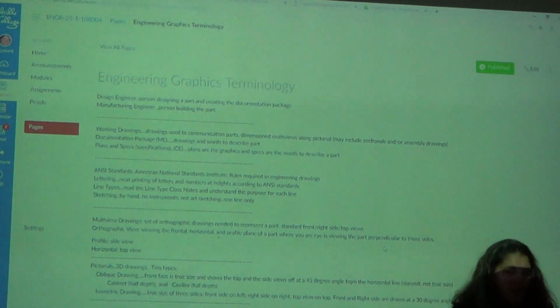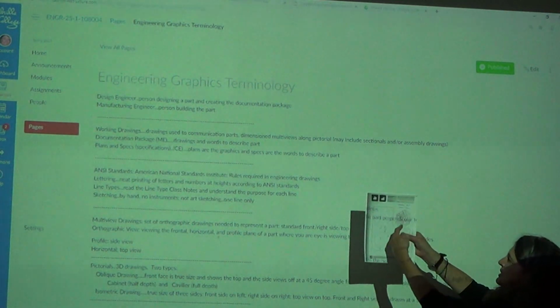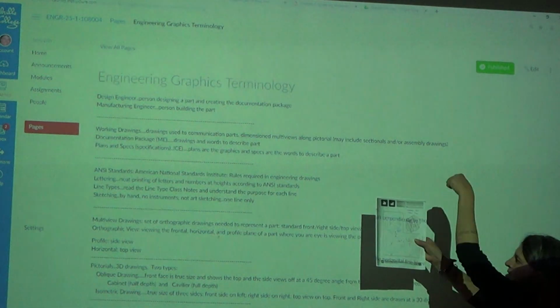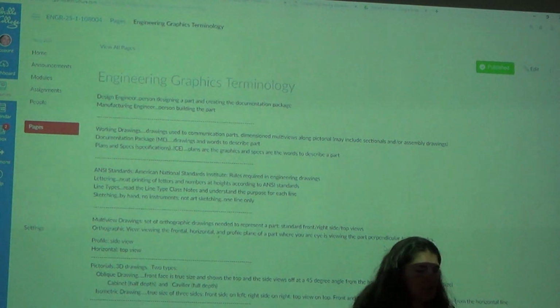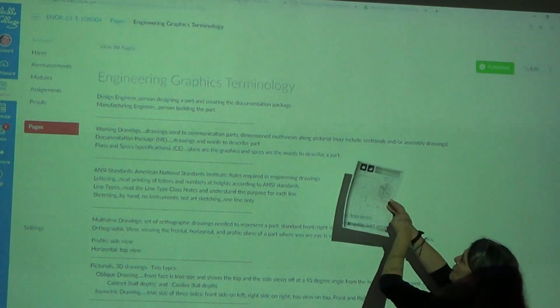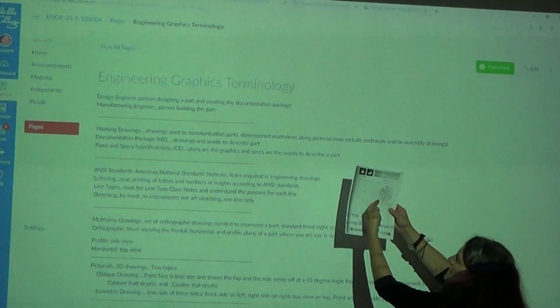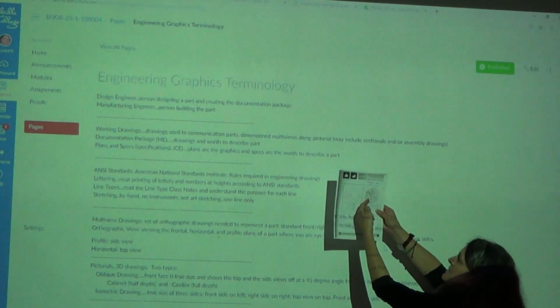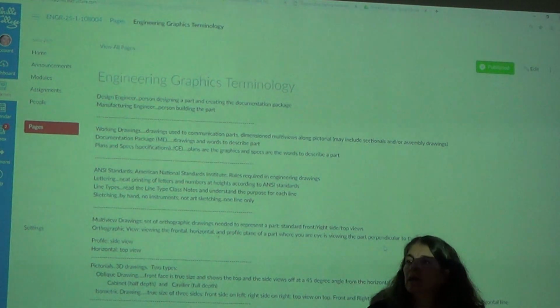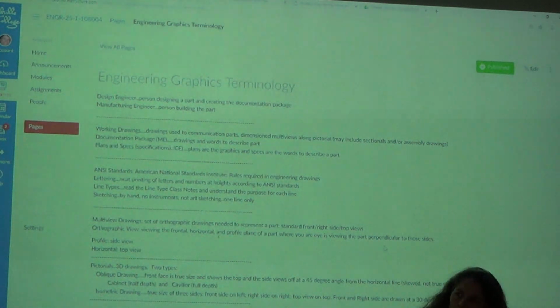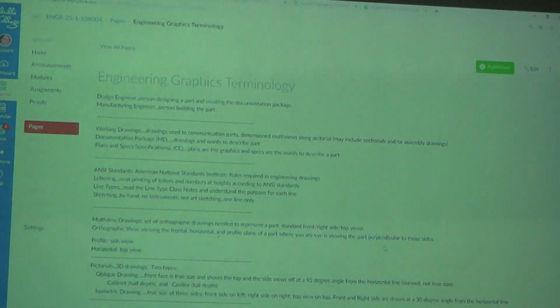Again, when you have an isometric, this is always the front, this is the right side, this is the top, okay? Because standard is always front, right side. If you pick this as the front, then this is the left side, and that's not the way it's standard in the US. Front, right side, top, okay? But when you draw now, let's say you're drawing the 3D view. You have to have the one with the most features in the front.